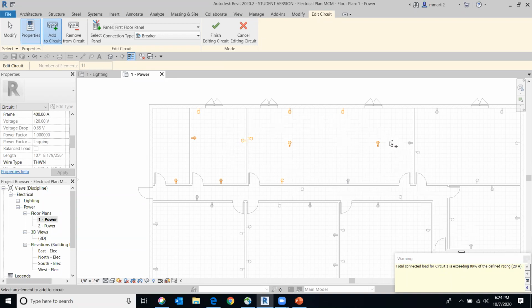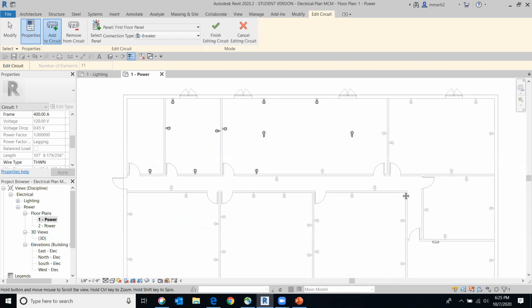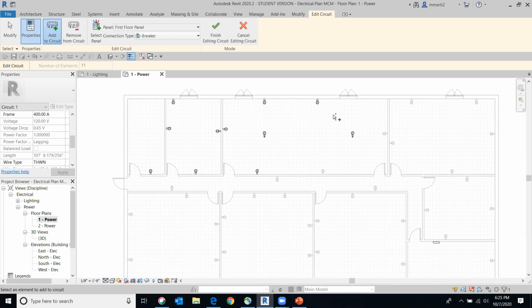And if we have too many in multiple rooms, you can see how that would be confusing if one breaker flipped and then you've got lights going out here, here, here, here. You want to try and keep things grouped together. So one of the things that I want to notice is, is there a way that I can keep all my rooms together within one circuit? You can see that I have 5 here. And then with all these other ones added, it kind of overloads that.